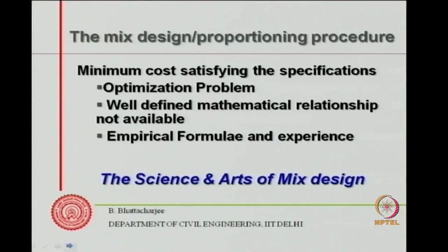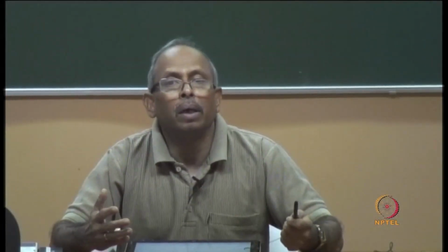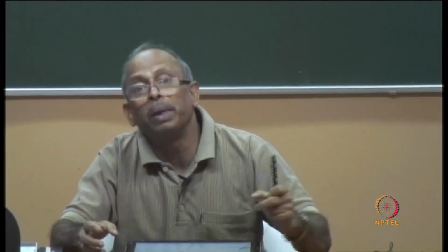A person who does mix design day in, day out for a given type of aggregate and cement system, or various cement systems in a particular locality, will easily come out with a mix proportion for any grade of concrete under that situation. Because experience is very, very important at the moment. Because we don't have a generalized relationship and materials vary from place to place, and even from the same source, you will find that the properties of the concrete vary. So experience plays a very strong role, and mix design procedure always involves some trial casting.